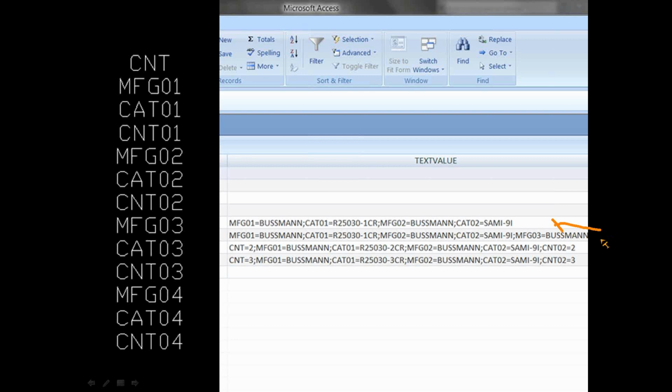And so you can see it's just a matter of having the attributes exist, and they have to be named this way to work. So having the attributes exist with this naming convention, and then having the text values pass right along back to it. So I can use that same symbol for multiple different methods of text values being passed by.